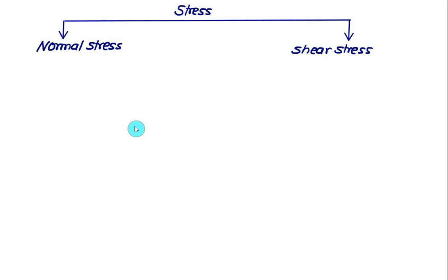In this video we'll review the stresses that we have covered in the mechanics of materials, and the Mohr's circle. So we classify the stress into two categories. One is a normal stress and second is a shear stress. Normal stress is further classified as the axial stress and is represented by symbol sigma and is given as the force upon area. Depending upon the force F, it can be compressive or it can be tensile, and area you have to select as a minimum resisting area.